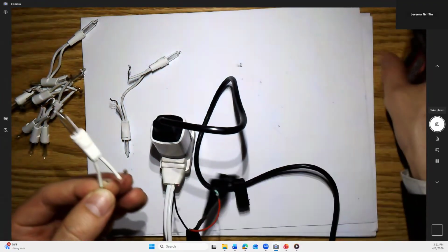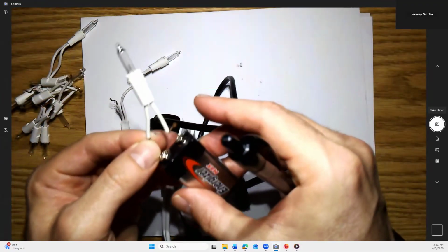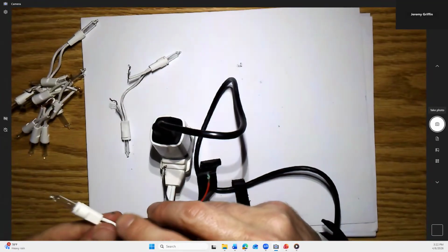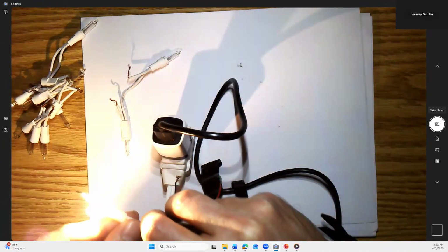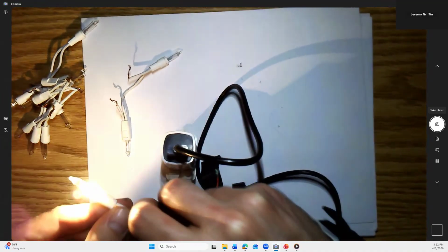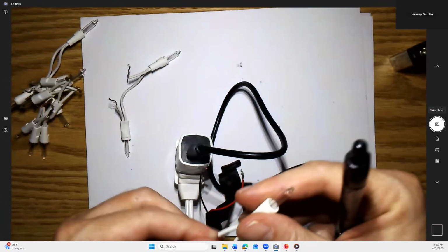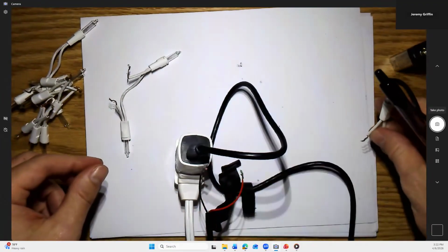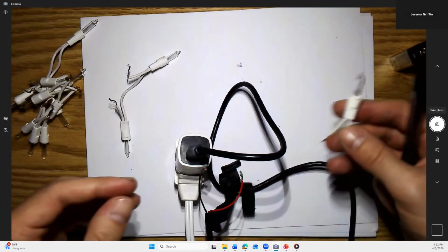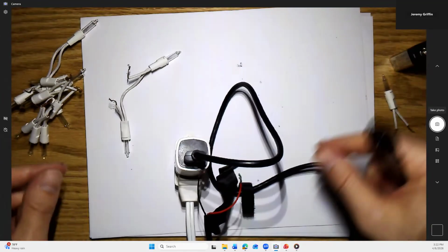What do you think would happen if I take the same bulb and put it on 9 volts? Is it going to be brighter? Because it's almost twice the voltage. Whoa, yeah, that's way brighter. Almost twice the voltage, so almost twice the current. And if you have almost double the voltage and double the current, you get almost 4 times the power. Ooh, a lot brighter.